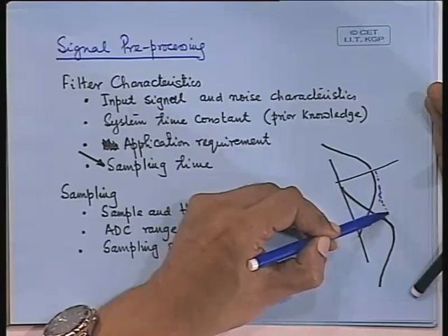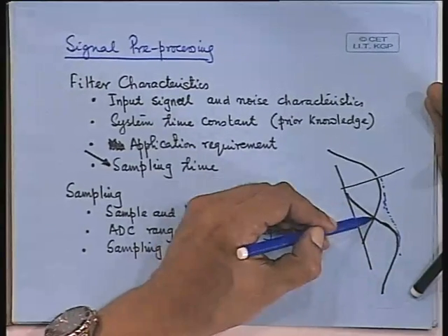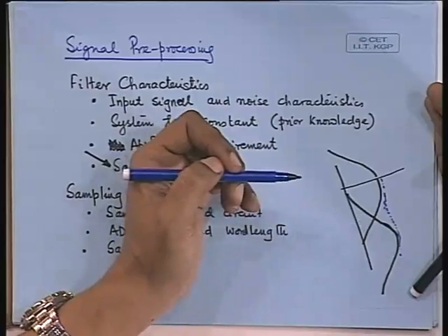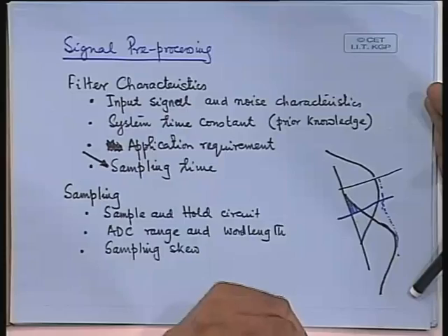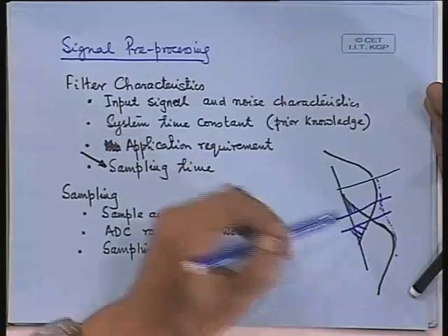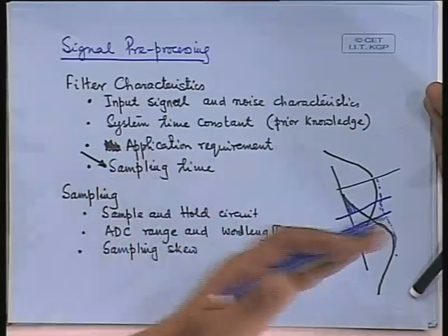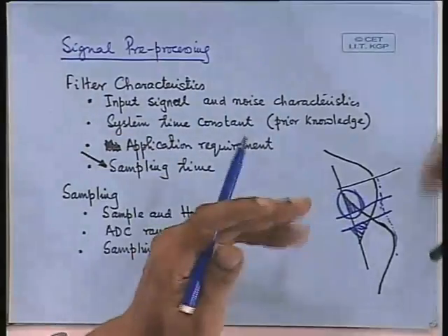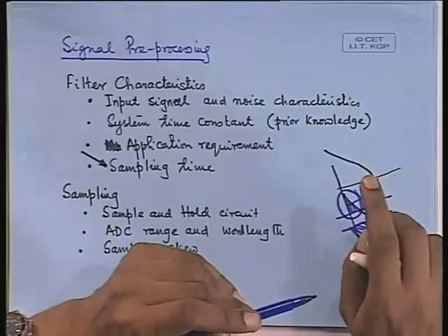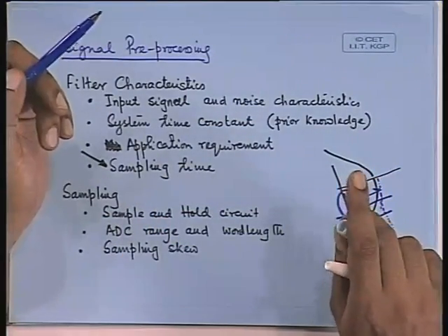Actually it is like this, because these two things you have to add up. This error is not so important, because you are finally going to put a filter. What is important is this error, because the high frequency error of the next band gets folded back onto the low frequency zone. So now you will have low frequency errors, which is not good.